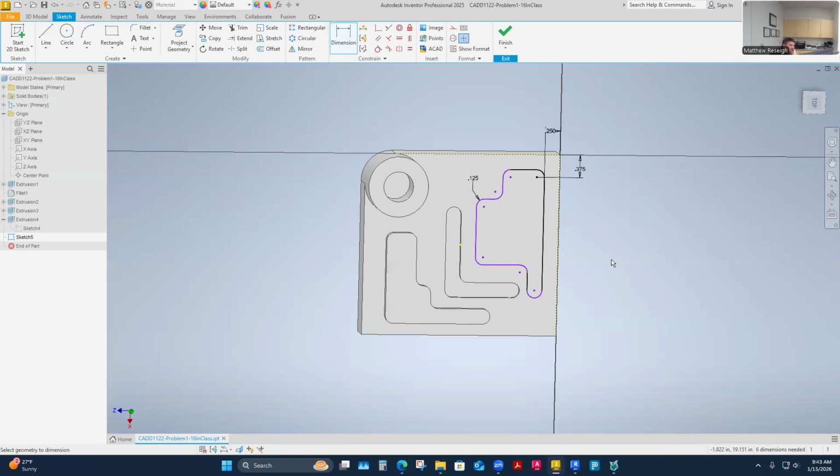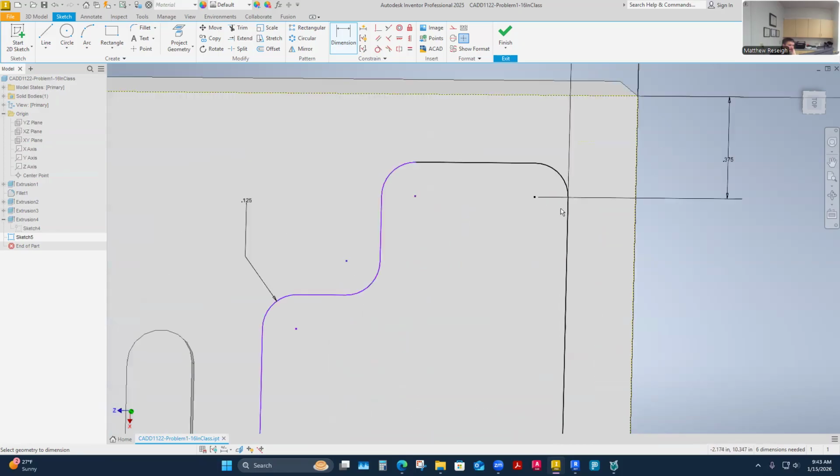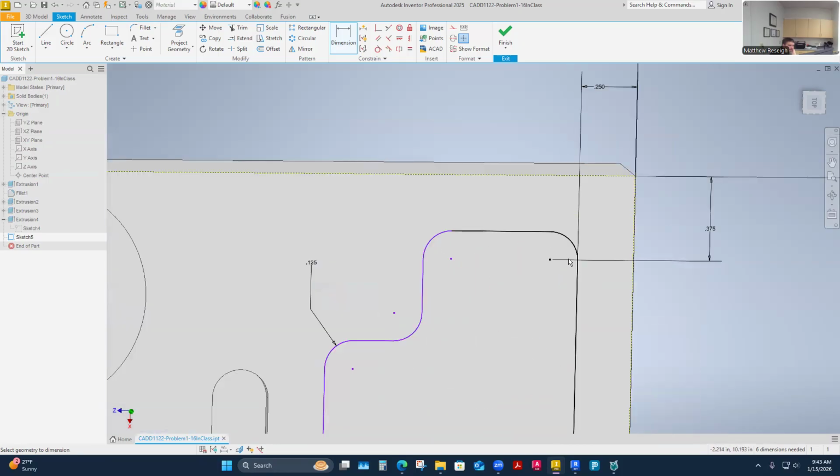But I can kind of chase this around. Yeah, so this is now all constrained because of the relationship that I have here, tangent to tangent plus the radius is figured out. So it knows that this is now all constrained. It doesn't know how far over this is, but we have a dimension: this over to here. You can see I'm just choosing the line segments a lot of times here. This is half inch, 0.5.